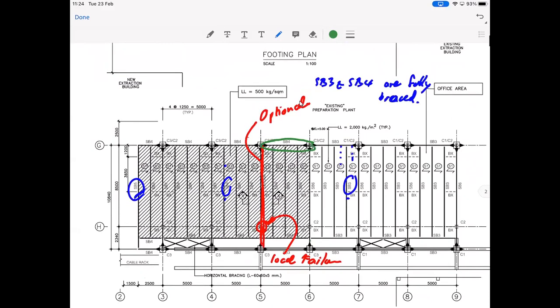because SB4, even though the unbraced length, which is the length between these secondary beams, is very, very short, you need to know what you should properly do with this beam. So we will leave it for the time being. Okay. And on second thought, let's try to do this beam as well. That's no longer optional. Do the simple analysis and try to pick the size of this beam.